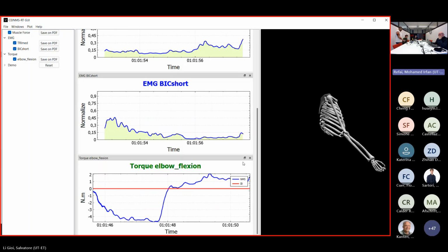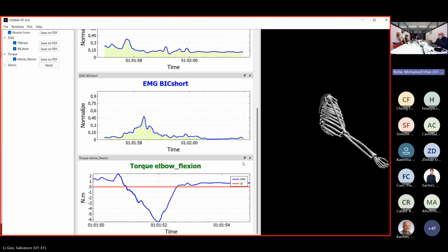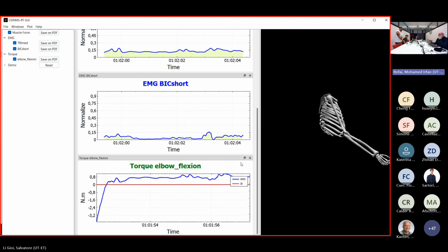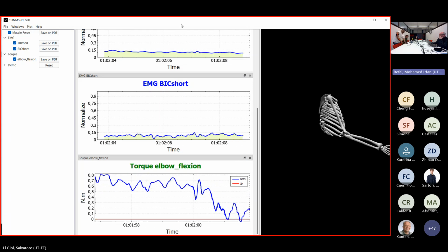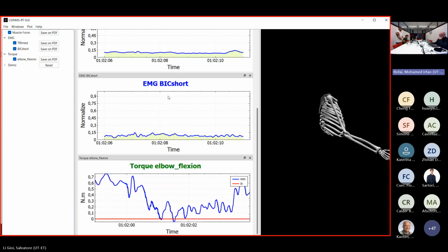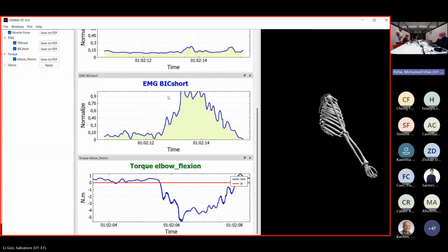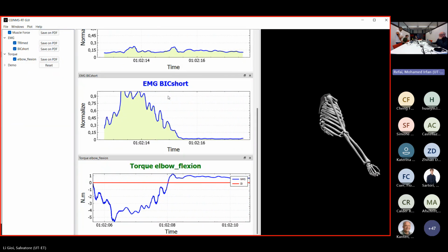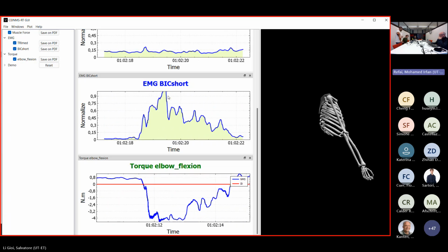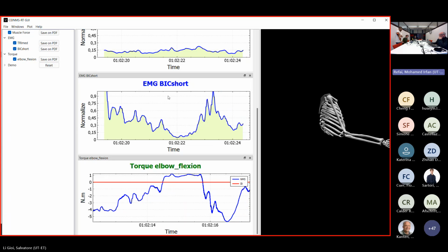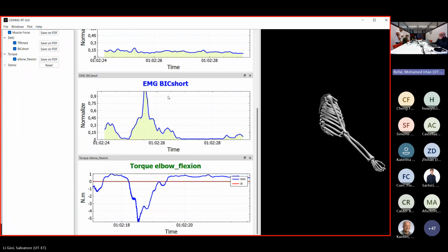You can see this is a very simple model. It has the kinematics, which gives you the force in the passive range, but also the activation of the muscle that you see here, which gives you the scaling of the force, and therefore you get the net torque, which is a sum of the forces times the moment arms around the elbow joint. Then you get the forces needed to lift anything that I have in my hands. And that's the CEINMS GUI that you're seeing right now.